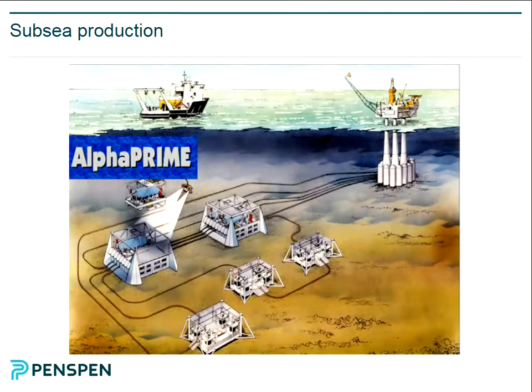Piece of pipe, L or DL. Pressure in, pressure out, height dz. It's got 3 bits. Considering really pressure drop here, really on a piece of pipe. So the pressure drop, it's got 3 components: the frictional component, an elevation component and an acceleration component.